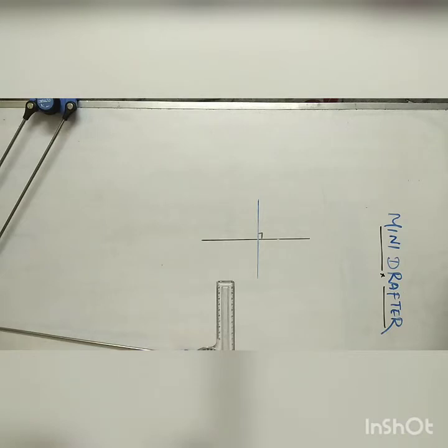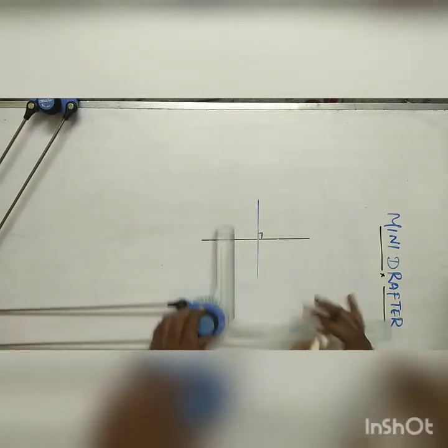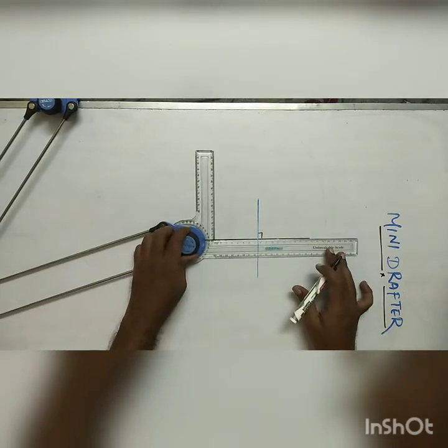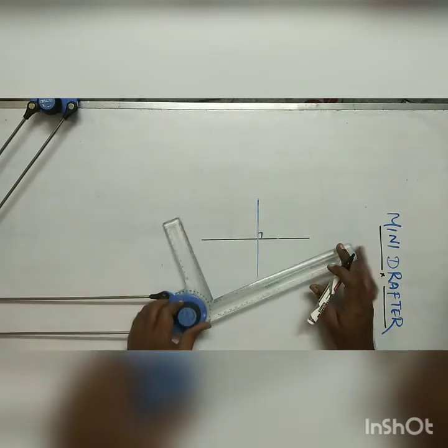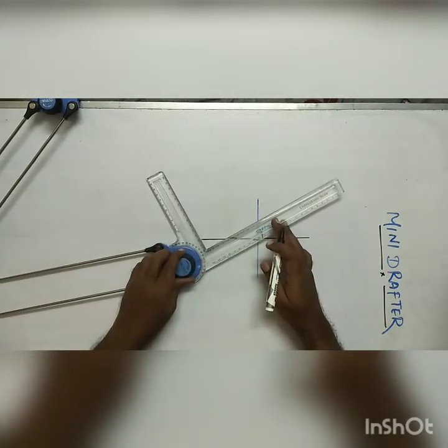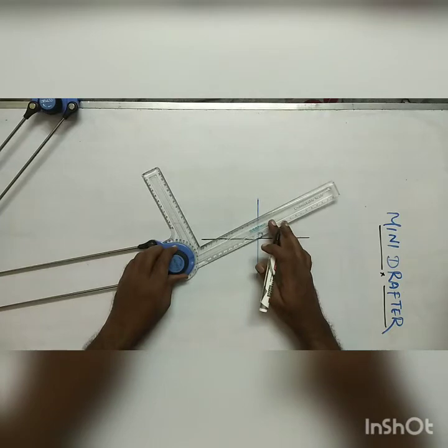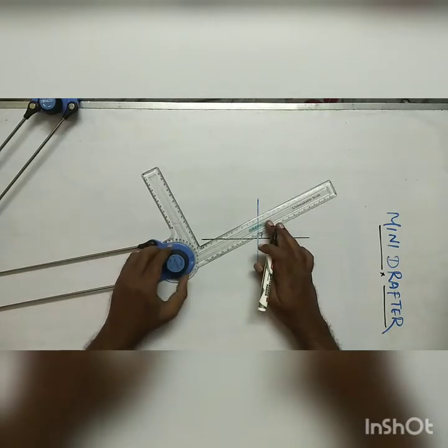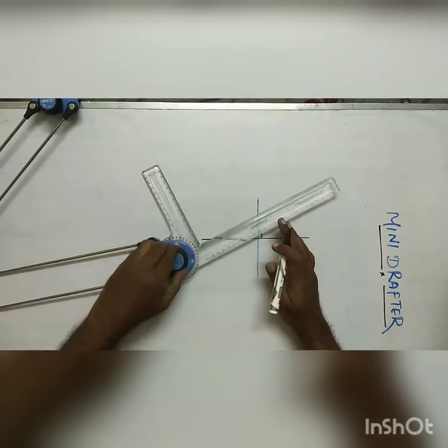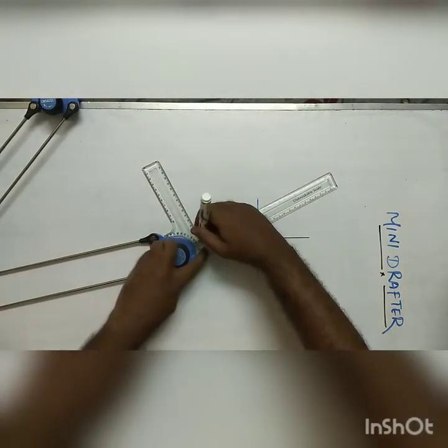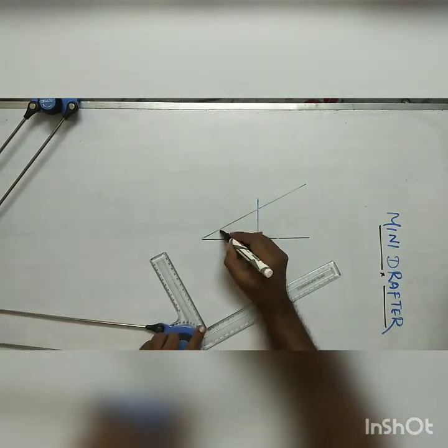And similarly, in previous classes I used to tell how to draw parallel lines. You guys may feel difficulty in how to draw a parallel line. For example, now this is 0 degree, right? Now some error of around 3 divisions will be there. Now I am going to place my protractor and rotate it like this. For example, I kept it at around 33. Actually, since there are 3 divisions of error, I kept it at 33. Now I tighten the knob. Okay, if I draw a line, I can say this line will be at an angle of 30 degree.